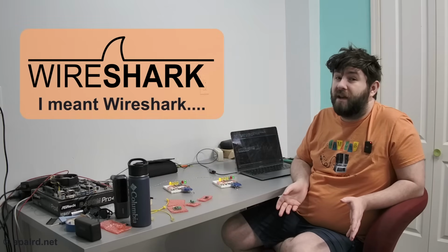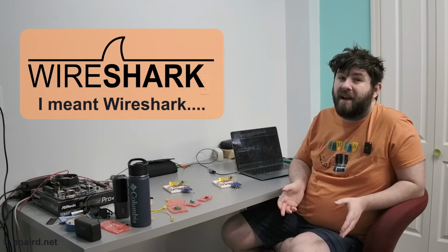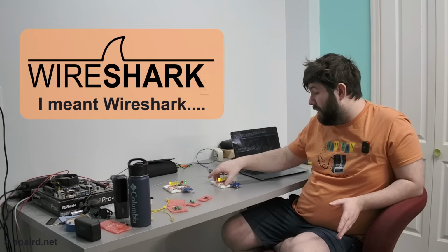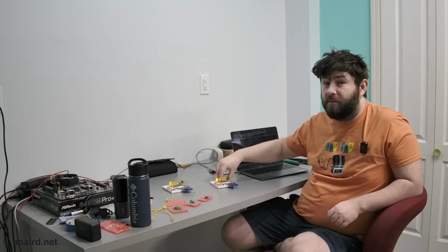Also, if you're doing this for real products, you can write your own Wireshark dissectors in Lua and load them in. So Wireshark can dissect all of your custom protocols you're using across your pseudo CAN bus at higher speed, which I didn't take the time to do for this video, but is absolutely something that you should do if you make a product based on T1S.